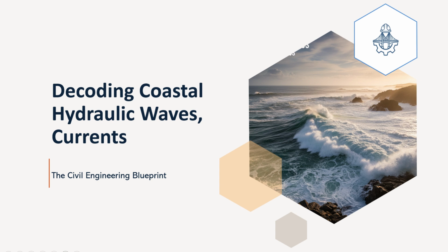The horizontal velocity vx simplifies, and in very shallow water, it becomes almost uniform with depth from surface to bottom. This horizontal velocity right at the seabed, let's call it vb, is particularly important, isn't it? Especially when we think about what physically moves sediment around on the seafloor and causes erosion or accretion. Absolutely critical. The horizontal velocity at the seabed, vb, is the key driver for understanding sediment transport dynamics initiated by waves. We can express its maximum value during a wave cycle as vb,max = (πH)/(T sinh kd), where H is the wave height, H = 2a.